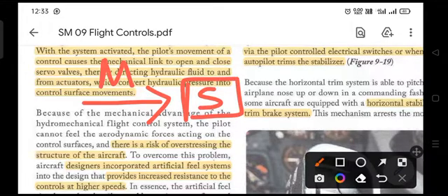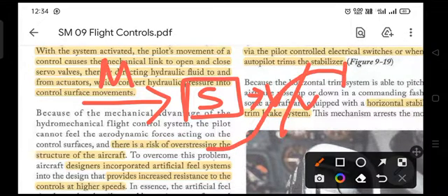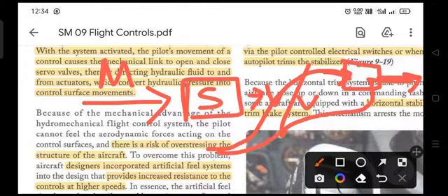Servos are very small motors basically that will open some valve. There will be some valve that will either open or close, fine, through which the hydraulic fluid will pass to the actuators that we have. If hydraulic fluid gets inside the cylinder, it will push the actuator, and if we bring back the hydraulic oil from the other side, then it will pull the shaft inside.